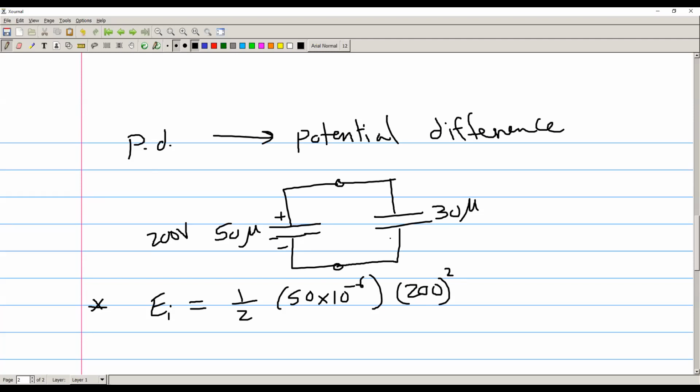The second capacitor has an initial voltage of 0, of course, and something will happen so that you have a balance between these two capacitors in order to maintain the steady state condition. It doesn't make sense to have 200 volts connected in parallel with 0 volts and have them remain the same. They will never remain the same, because there is a potential difference here.